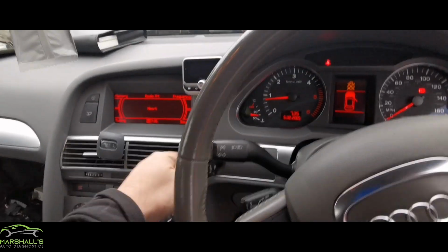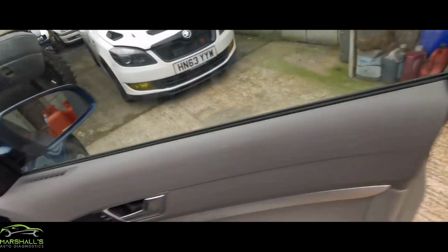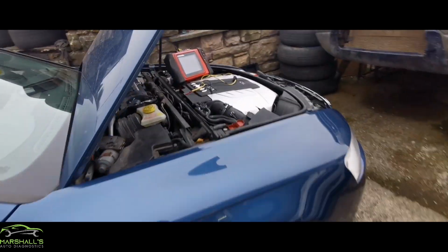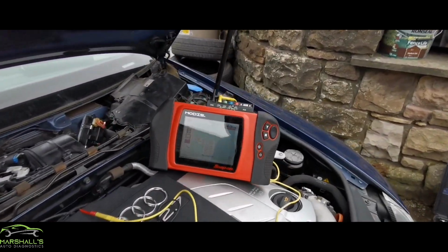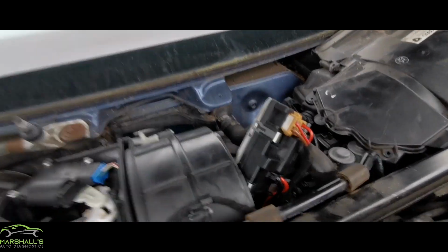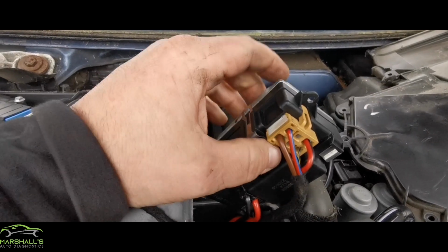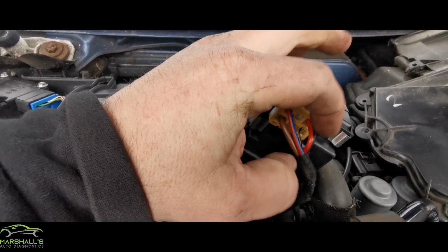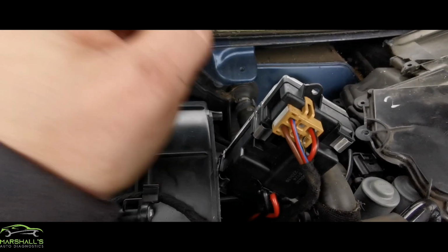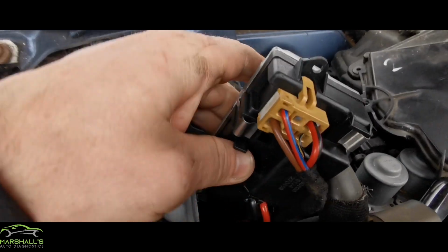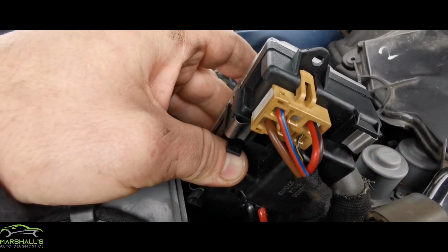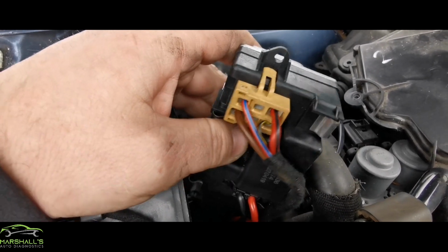So turn the engine off for noise. Okay, so I've got the meter ready to go. The blower motor's at the back here under the plenum chamber, and we can see our power and ground. This doesn't have power on it, but it comes from somewhere else. I'm not really too interested in that one. It's this small wire here, the black and yellow wire. So that's our communication wire.